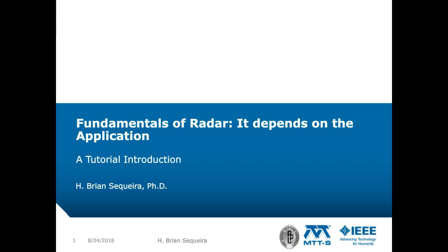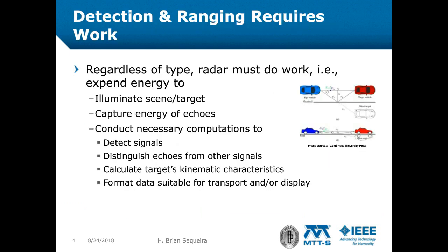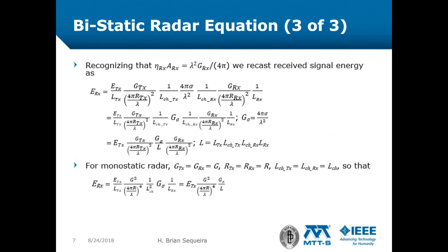Computation involves estimation of noise, setting of thresholds, and cataloging signals that cross such thresholds. Not all threshold crossings are echoes, and so additional computation must be performed to determine the pedigree of signals and so distinguish between interfering signals and echoes.